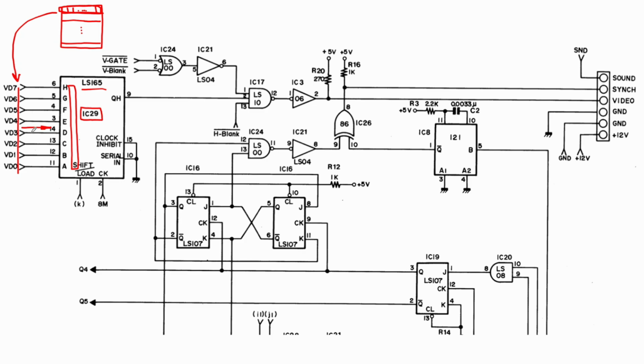So this entire byte is loaded in one go into a register inside the shift register. And what the shift register then does, it takes the first bit of that byte, bit 1 over here, and it will send it out through this QH port. And if you follow what happens here, it has some more processing, some signal conditioning. You can ignore all that. Eventually, it makes its way to the video signal that goes to the screen.